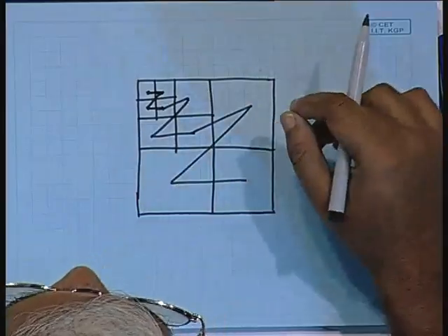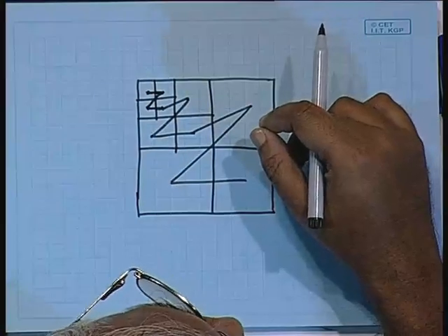And as we go on to finer and finer resolution, and that too in the high pass filtered subbands, we will be finding lesser and lesser significant coefficients. So, there is a possibility that we will be picking up a considerable number of insignificant coefficients or zeros, okay, when we traverse down this tree.